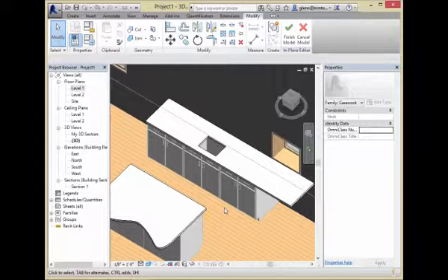I could model that backsplash in a lot of different ways. I could extrude it from the top, from the flat surface up. I could even extrude it lengthwise. I could go to the end and extrude it lengthwise that way. There's a number of different ways you can do it. And that's the cool thing about all this modeling in place: you can use whatever method is easiest for you to define the geometry. You're just creating different solid and negative pieces.